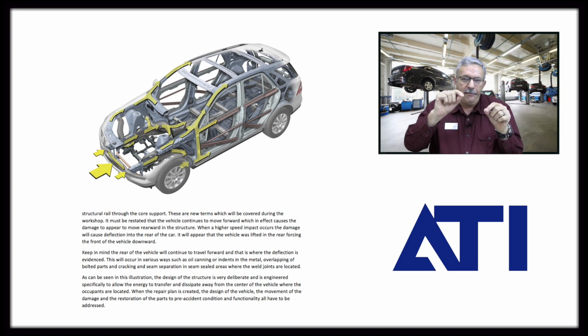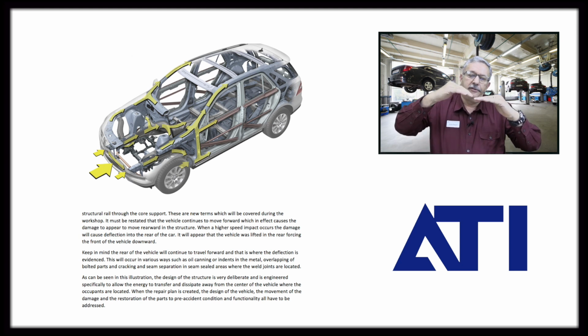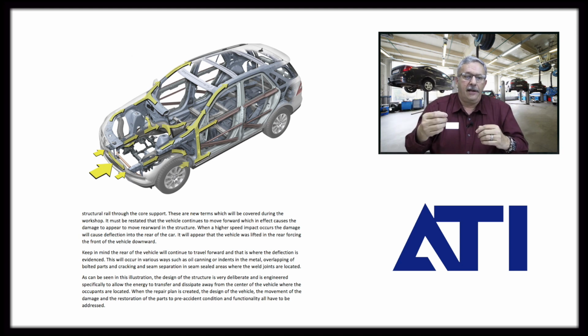As that occurs, remember the damage is going to dissipate. Things that I have to look for on a substantial impact: did it crack the windshield? If it cracked the windshield, that means that the roof section, as the damage was coming back and moving forward, had enough stress put into that windshield that it cracks it. Very common occurrence.